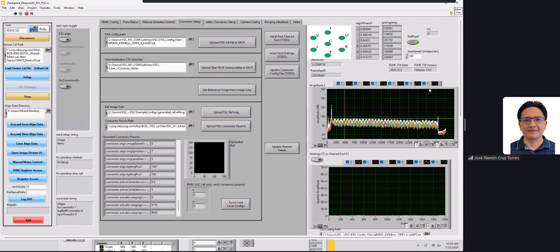Some of the main causes for a free space connector can be that your reflection is really bad and raising your noise floor too much, so you can't resolve the actual peaks, or your grating amplitude is just really poor. You can also be barely coupled, with your cores slightly off. Think of it as overlaying two circles on top of each other: the more they overlap, the better your signal is.